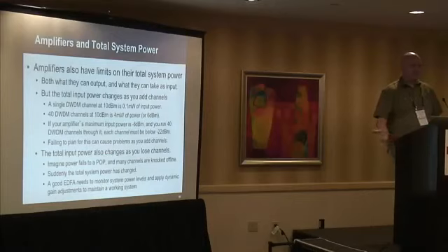So for example, if you have a standard dumb amplifier that's passing 40 signals and all of a sudden you lose power in a rack and 20 of these signals drop off, it's going to change instantly the total power in the system. So you need a good EDFA that can actually look at what you're trying to achieve and adjust the gain dynamically.